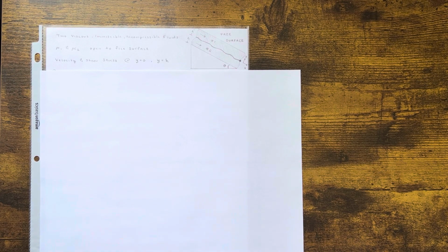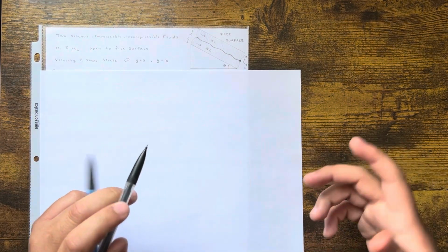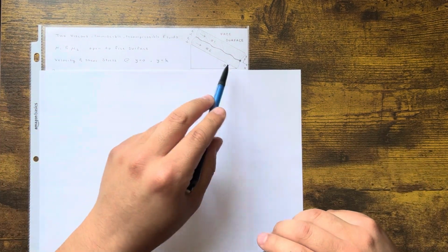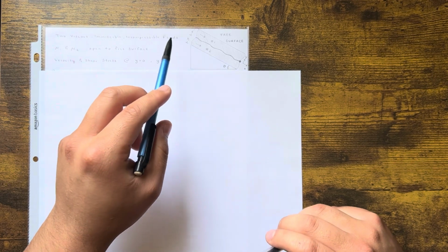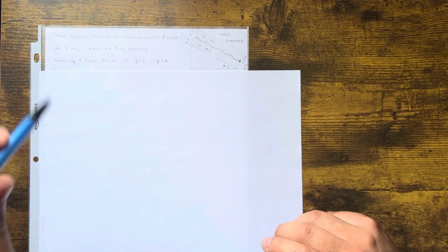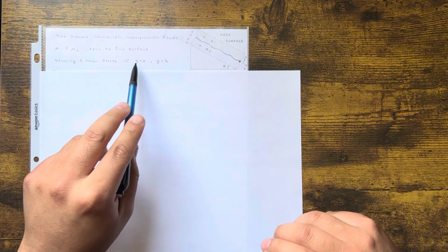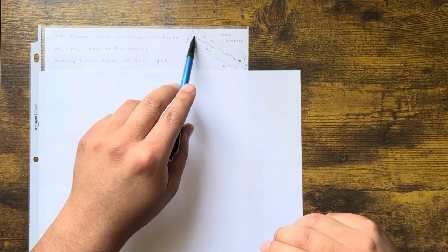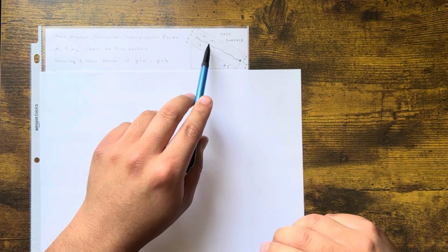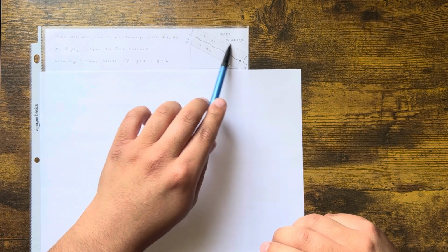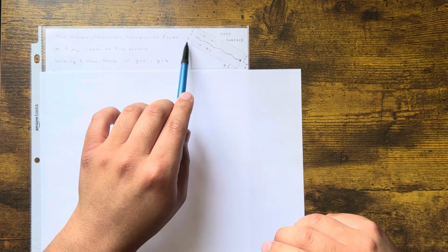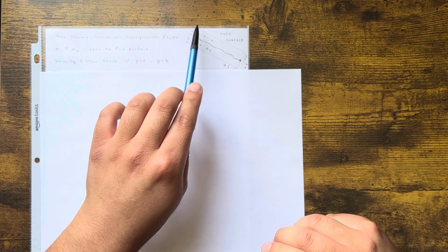All right, this one's no different than the other one, just that the surface is now inclined. In this case, I'm going to get the velocity and the shear stress at y equal to 0, which I'm going to set right here, and then at y equal to h at the top of the free surface. You could do from 0 to h to 2h.